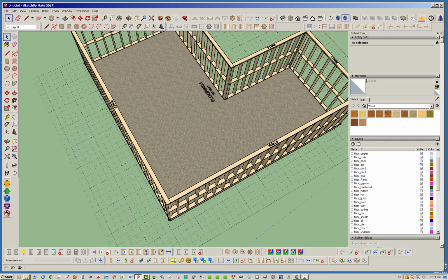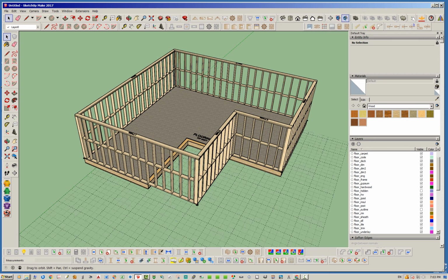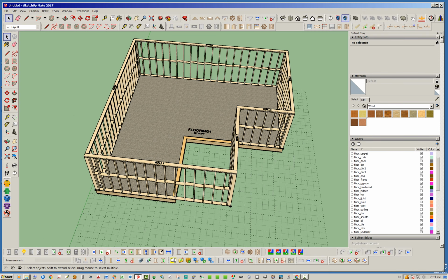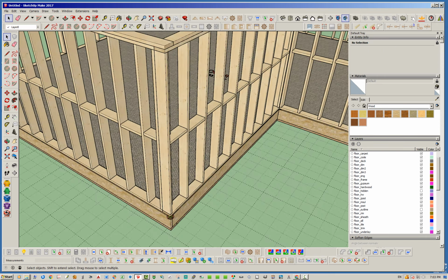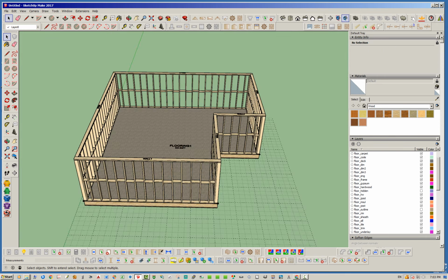But for instance, now let's say we move this wall right here. Let's bump it over 8 feet. And so then to simply change this, let's regen the floor. It doesn't matter which one you regen first either. So let's just go ahead and regen the floor and just right click on it and hit regen. And then to regen the flooring, we've got to click the regen flooring button, mouse over it, and there you go. So it basically is following those walls around.